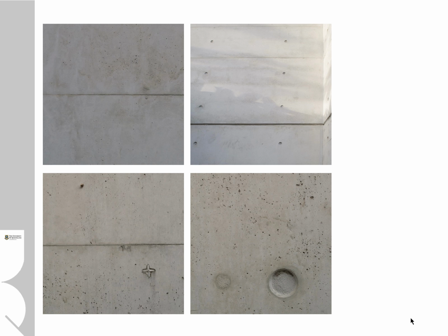Now we can see on the top right hand side the pattern of circles that's going up the wall. These circles are cross ties in the formwork. When you are setting out formwork for an in situ concrete wall, it's important to have a series of bolts holding the two sides of the wall together.